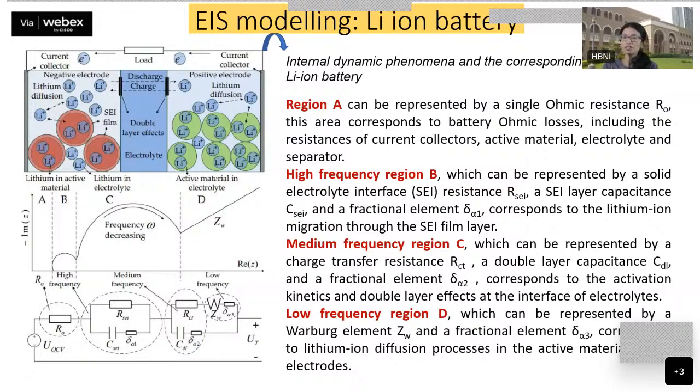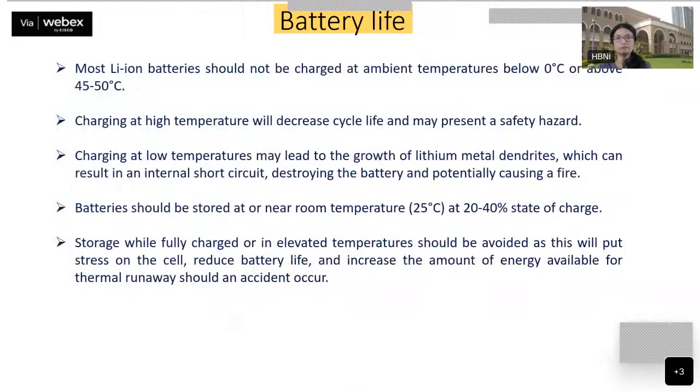So first, before you start cycling, you can see how it's looking. Then you run it for 5 cycles, then you see how these different resistances are changing, and then you can run it for 1,000 cycles and again check the EIS measurements. You can see how the charge transfer as well as the diffusion, these different parameters, are changing in the battery, and with that you can have a host of knowledge of the electrode material, whatever you're using, whether it's a good material which can be practically used or it is not really functioning well.